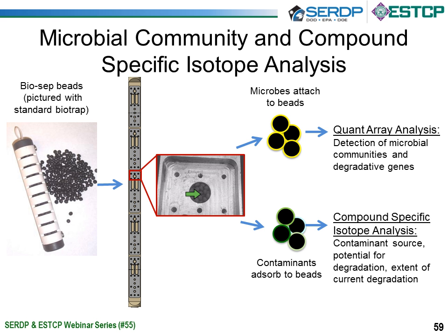The beads will basically absorb microbial communities and chlorinated solvents over the 3-week equilibration period. When the sampler is removed, the beads can be removed and shipped for commercial analysis. In our case, we use the quanta array analysis, and then also evaluated the isotopic composition of the chlorinated solvents by CSIA.